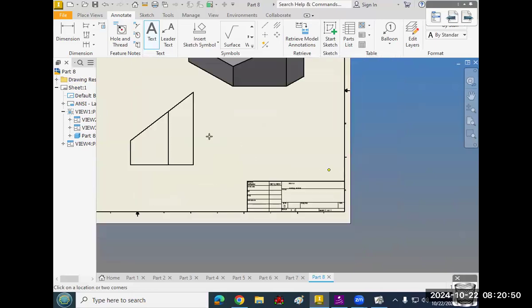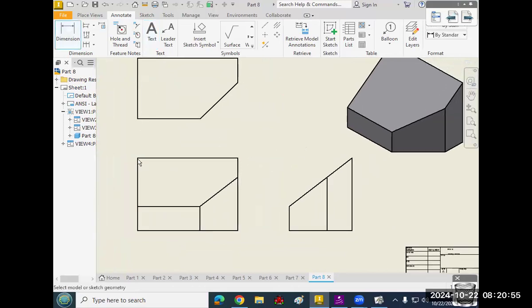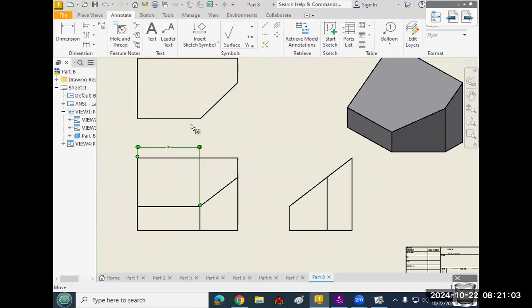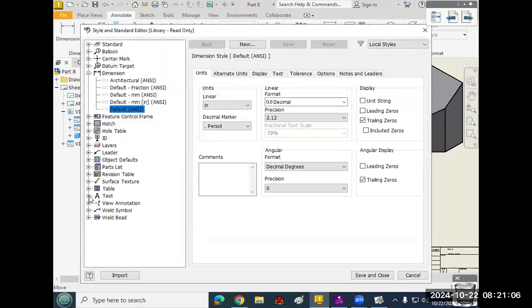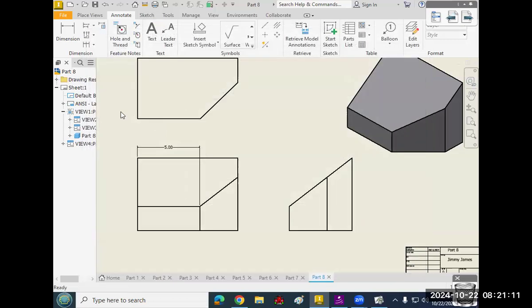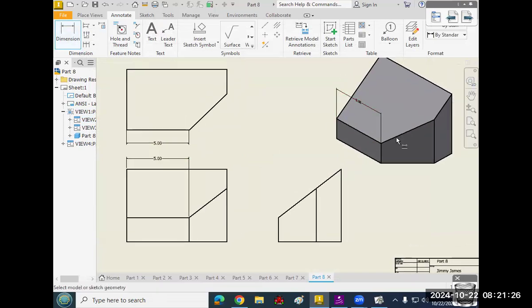And let's get going. Okay, left to right, the first thing that happens is this edge right here, which has a long extension line. So we're going to put it on the top view, which not only is a shorter extension line, but it's also to a contour, which is what we're looking for. So this dimension is actually going to be there. And again, I don't know if everyone's getting this, but these dimensions aren't just the same number. They're pointing to the same thing. Okay, they are the length of that distance.